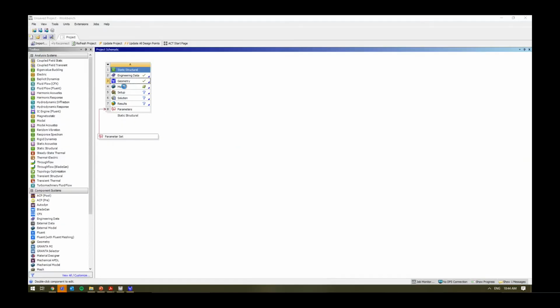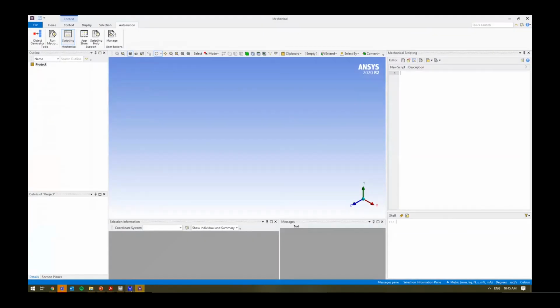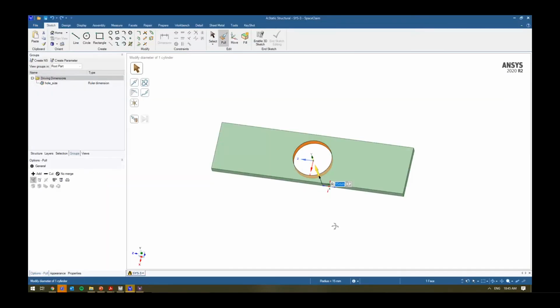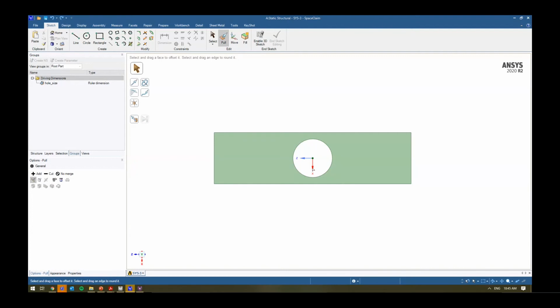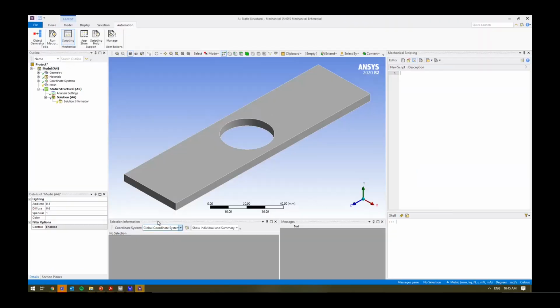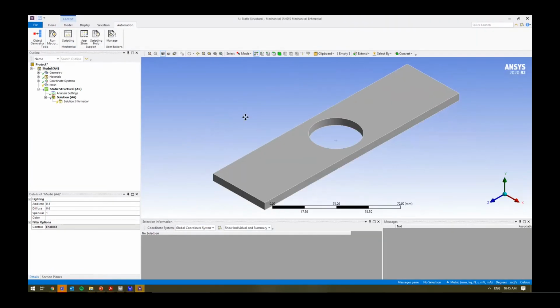All right, let's set up an analysis. Bring this up into here. We'll start mechanical. In reality, if you're doing this as a project, it's axisymmetric. So not axisymmetric, it's symmetrical, so you wouldn't necessarily want to model the whole thing. You can even potentially do a quarter model of it, but you can even do this in 2D as well, right?